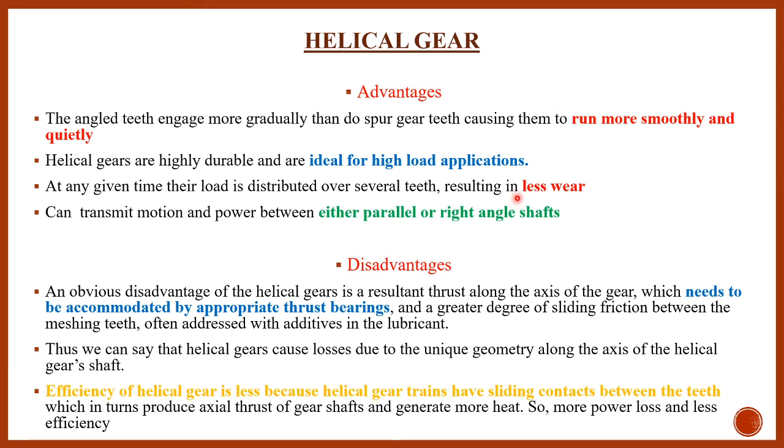Advantages: they run much more smoothly and quietly. Helical gears are highly durable, which makes them suitable for high load applications. The result is that contact starts at a point and ends in a line. That's why there is less wear compared to the spur gear.